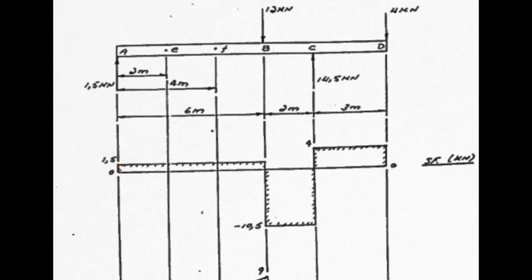And then between A and B there are only point loads, there are no loads, and there's no UDL, so we simply stay constant at 1.5. We encounter a 12 kilonewton load at B, which takes us from plus 1.5 to minus 10.5. B to C, no loads again, we just stay constant at minus 10.5. There we encounter 14.5 positive, so up we go, puts us at 4. Across we go at 4, and then we encounter the final 4, takes us back to 0. So that is the shear force diagram sorted.